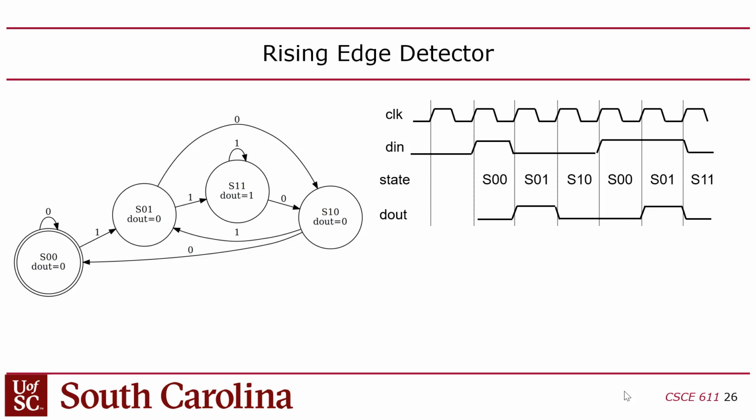So I don't know what state I'm in until I have 2 cycles of samples here, right? So by the time I get that clock edge and that clock edge, I'll finally know that I'm in S00, right? So basically, I've initialized this to state 00, not through the reset, but by having the input at a known value for 2 cycles, right? Okay.